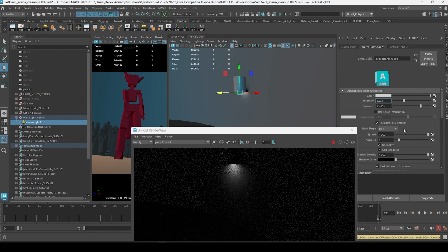So I'm going to turn on this use color temperature and make sure that I go into the red spectrum. And this is also an easier way to control the color of the lights through the attribute spreadsheet. Number is just a singular integer that you can dial back and forth, and you don't have to go playing with all the actual light color.